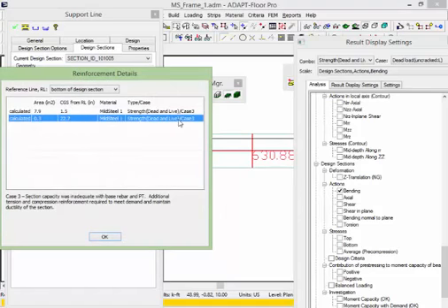So what this means is that the section capacity was not sufficient for base reinforcement. There was no base reinforcement. So the program is actually having to add both tension steel and compression steel to meet the ductility required to keep this a tension controlled section. That's what this case is indicating.